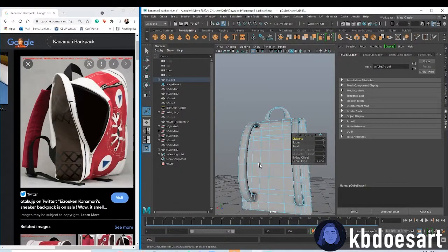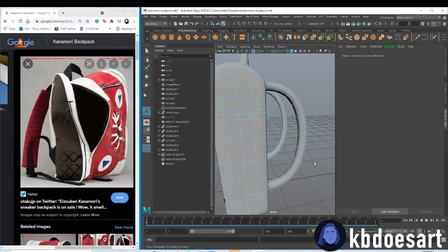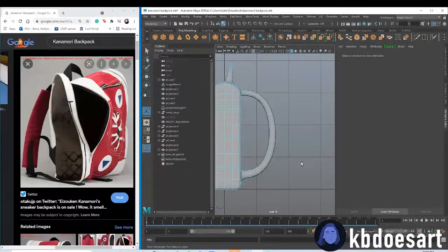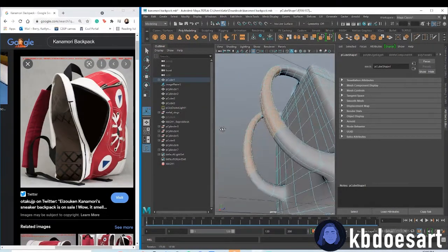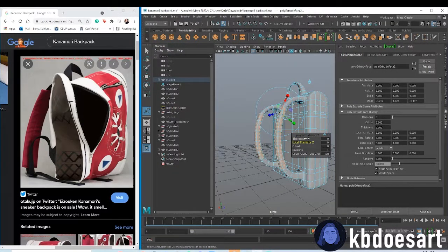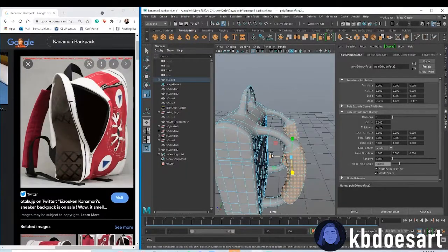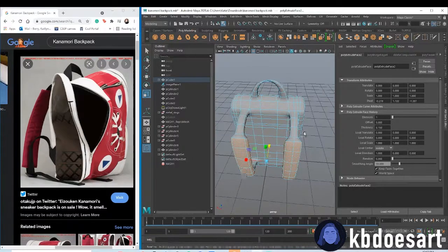And then as for the red part, go into this side view and I would just click and drag to get the faces that you want. Double check you didn't grab any extras and then just do Control E and up the thickness on that. Then you could just click R and flatten them out a bit so it's a little more precise.